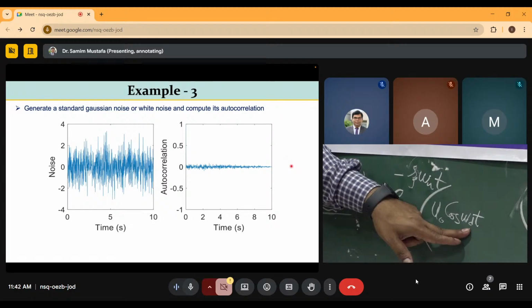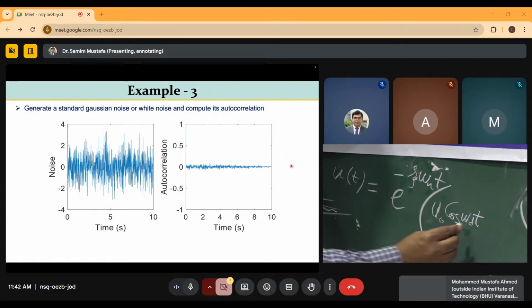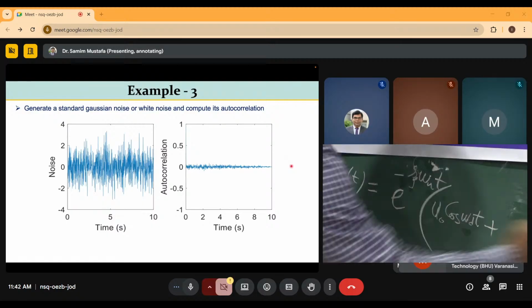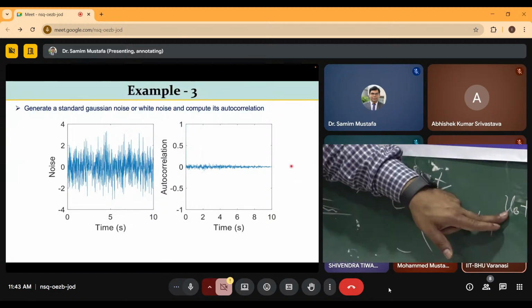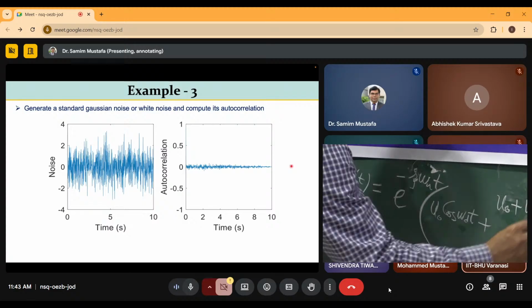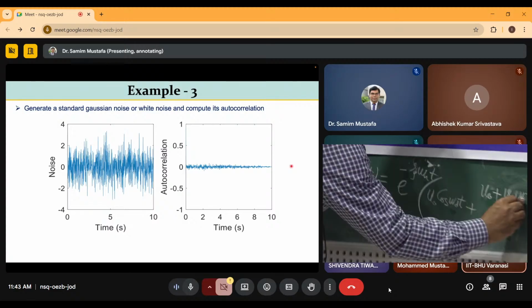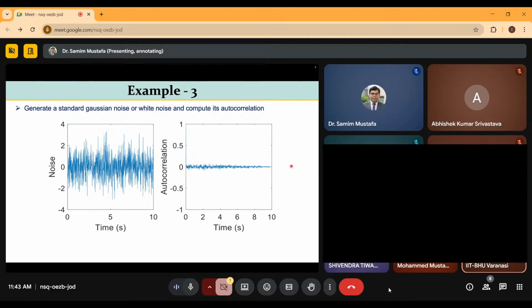The damped natural frequency is omega_n times the square root of 1 minus xi squared. Plus there is some function, with u_0 and v_0 meaning initial displacement and initial velocity, then omega_n, and then something with omega_d.